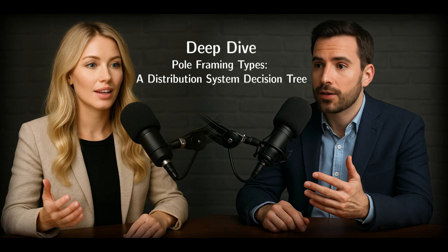Precisely. That's exactly it. Its ingenuity lies in its purpose. It's used when you simply cannot install guy wires at that receiving pole, the very next pole down the line. Maybe because of intractable site constraints, think poles right in front of public sidewalks or busy driveways, or maybe areas with really rocky terrain where anchoring guys is basically impossible or would create a hazard. So the pole you're looking at, therefore, has to absorb the entire unbalanced load from that dead end side, and then it releases it into a slack span that requires no real tension support at the next structure.